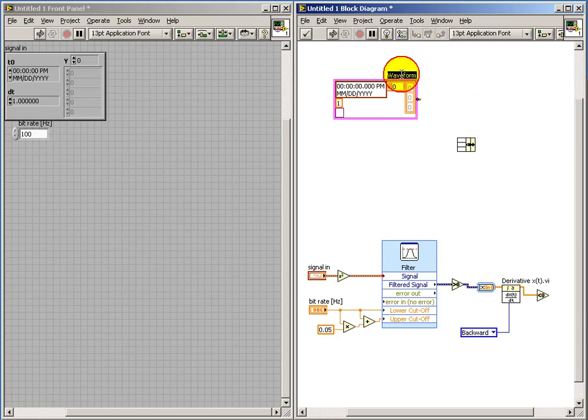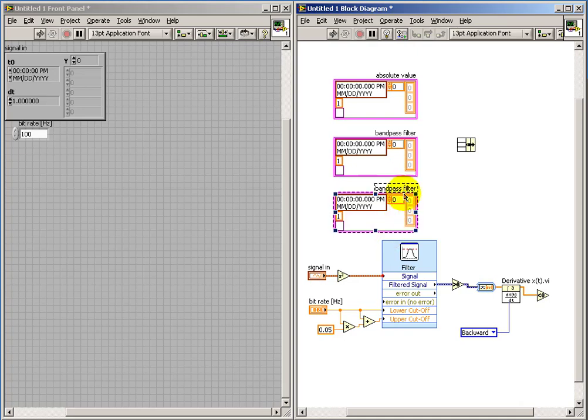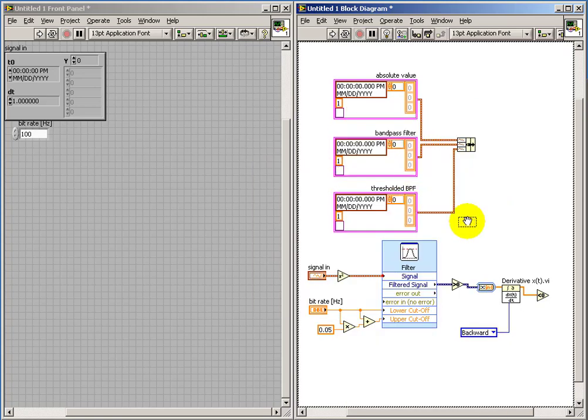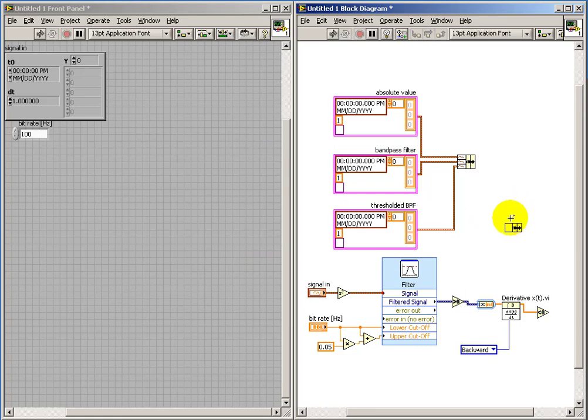Now I'm setting up a waveform data type constant. I'm also giving it a specific name, and this is what will ultimately allow me to use the bundle by name node. That way I keep everything straight on which signal we're looking at. So even though the constants are big and bulky here, they really are simply saying set up something that looks like the waveform data type and give it a specific name. So at this point I've established the cluster in terms of what it should look like data type wise. We still need to actually get the signals applied to properly generate our output.